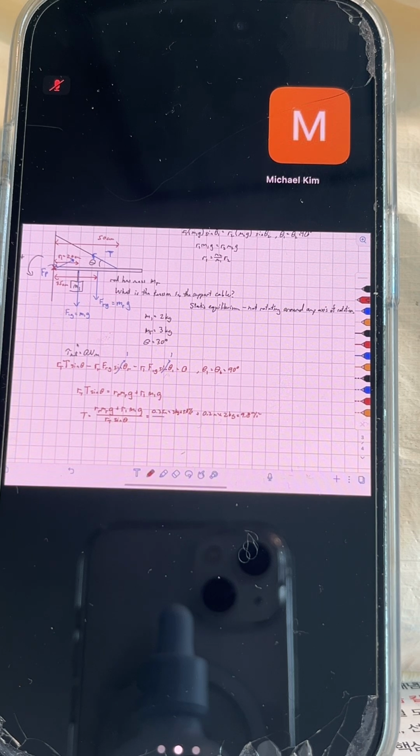All right, adding this, and then I'm dividing this all by 0.50 meters times sine of 30 degrees. Okay. And then just very quickly getting my number here, I get that this is about 56.8 newtons. Okay.